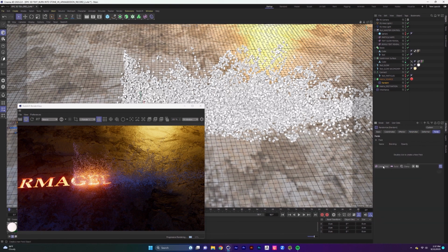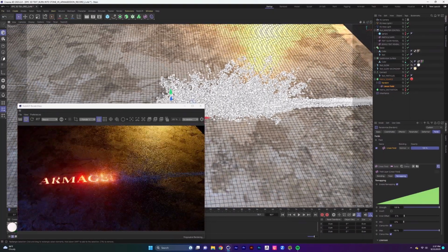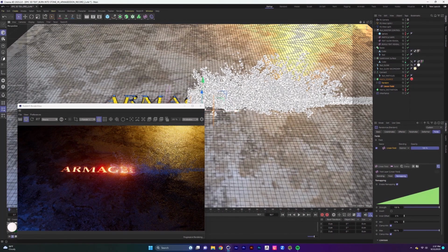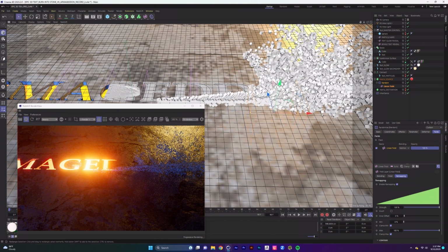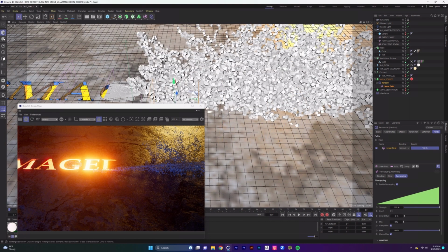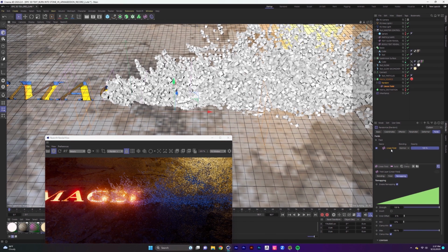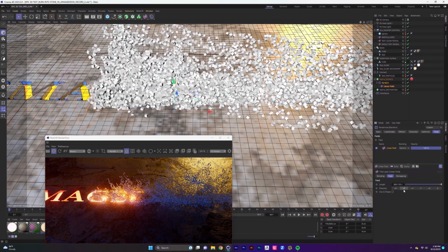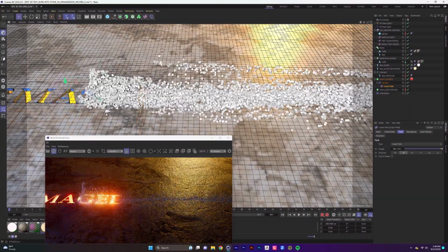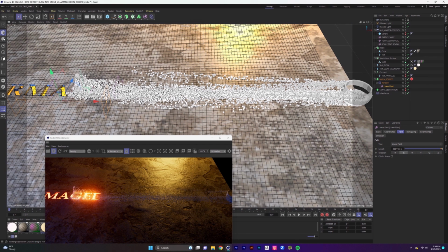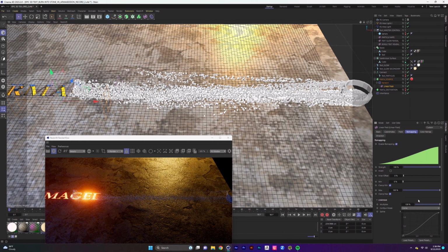Under fields, we're going to add a linear field. And as we move the field through the particles, notice how it's creating a fall-off ramp, affecting the particle flow and the random noise. And we'll move our field somewhere so that it looks as if the particles are gradually being pulled up and out. And we actually want to switch the direction of this linear field to -X. So on the linear field, under remapping, change the contour to curve just so it's smoothed out a bit.